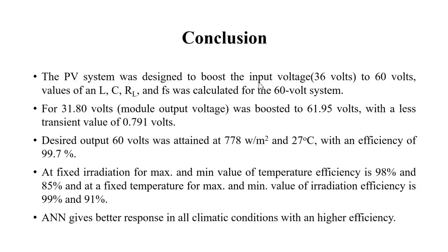This PV system was designed for a 60 volt system that was boosted to 60 volt from the 36 volt system. The inductor, capacitance and load resistance and frequency have been calculated for the 60 volt system. That means if the boost converter value has to be changed, then all the values of inductor, capacitance and resistance have to be varied in that ratio.